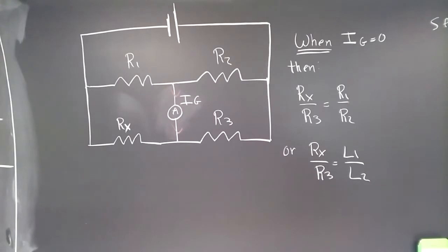Now, ordinarily, if you were to connect four resistors together this way and just four random values, there would almost certainly be some current there. It would be pretty amazing if there weren't. So let's say there's a current there. But we said these resistors are adjustable. The known ones are anyway. Let's say we adjust R1, R2, and R3 so that we get zero current across that gap in the middle, okay? So in other words, we're going to play around with R1, R2, and R3 until we get zero current in the middle, all right?